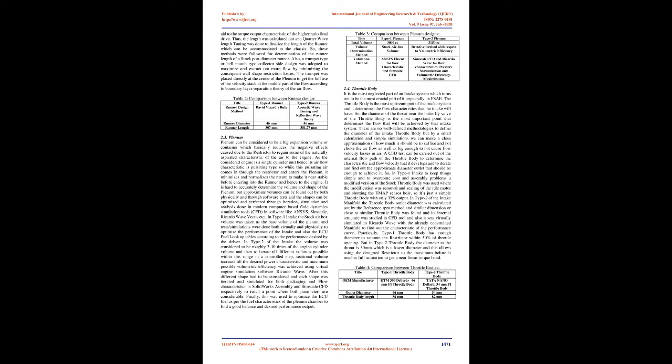For the Type 2 intake manifold design, a different methodology was considered. This time, the major topic was the volumetric efficiency result with respect to the available air pressure wave during the inlet valve open duration, so acoustic wave tuning and reflective wave theory were considered, which deal with tuning the runner length with respect to the reflective wave frequency and its time of presence with respect to the inlet valve opening duration.